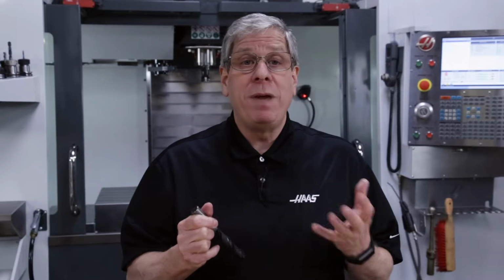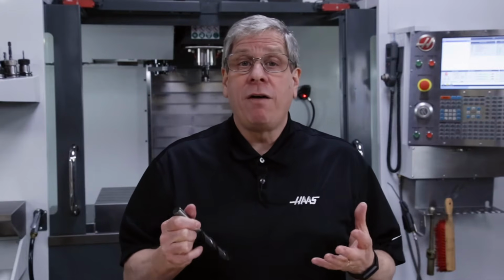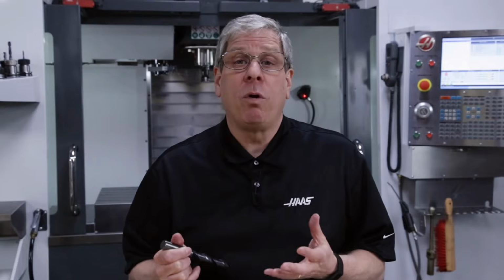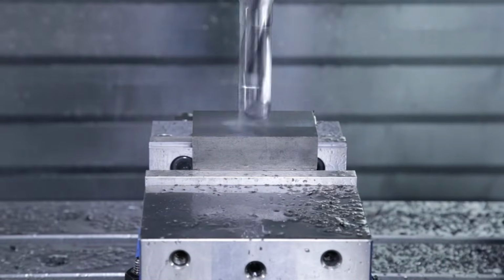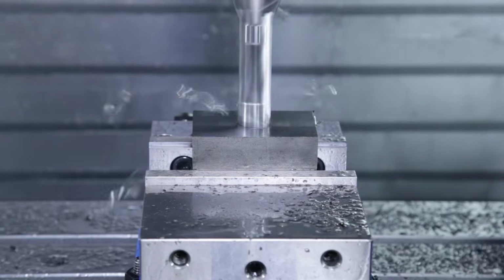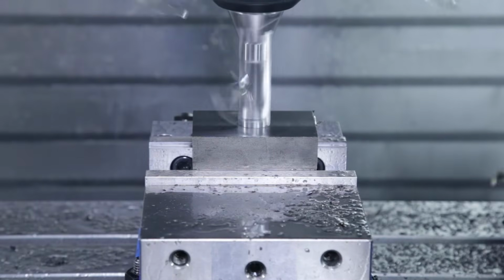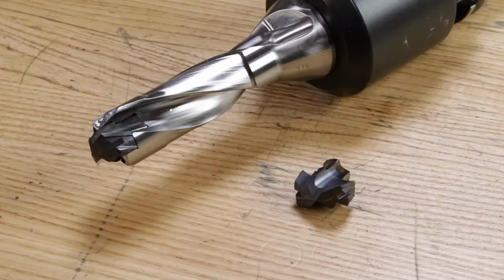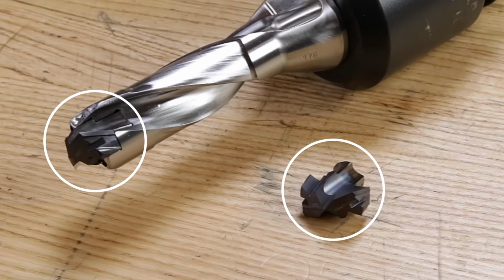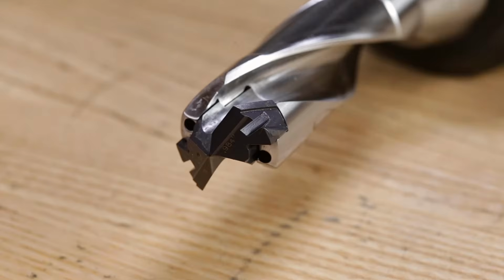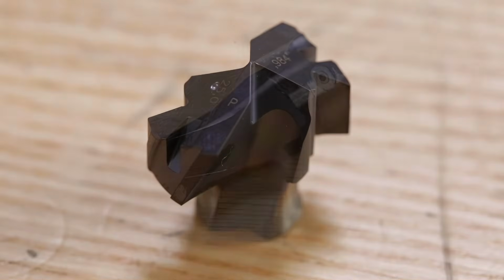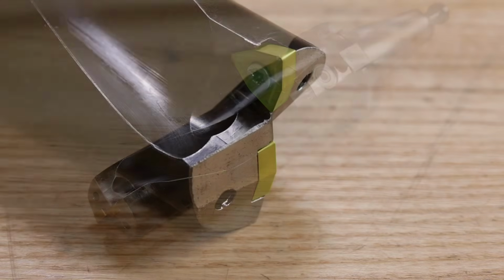They're also made from many different materials and often have special surface coating to extend their life and lower the per hole cost when they're used in a production environment. Once drills get to a certain size, it becomes more economical to use drills with indexable inserts like these. This way, when the drill's cutting edges get dull, you just replace the insert. This example has two inserts.